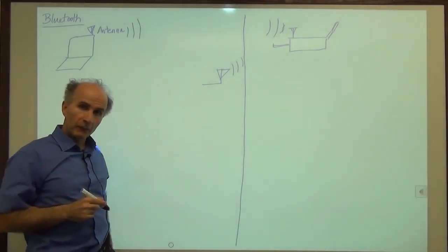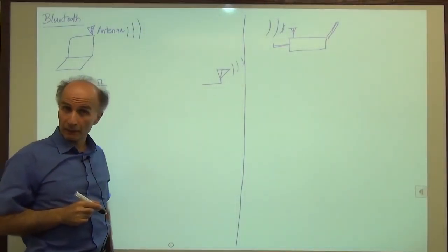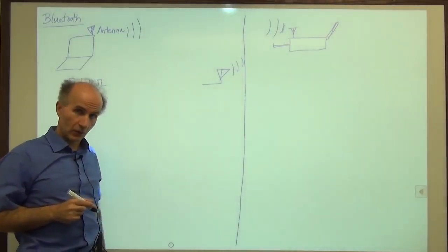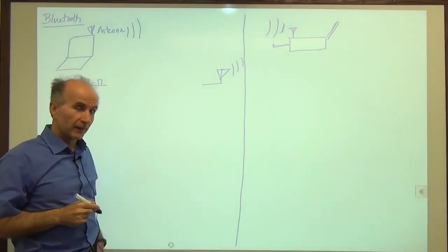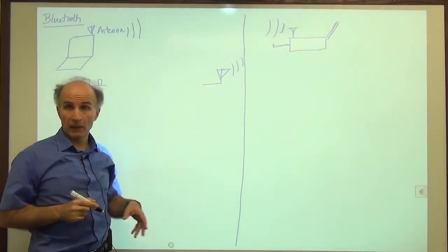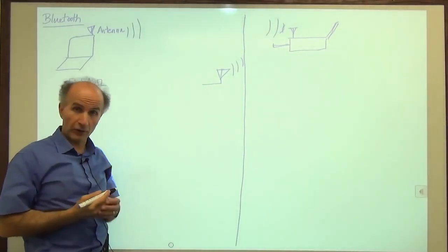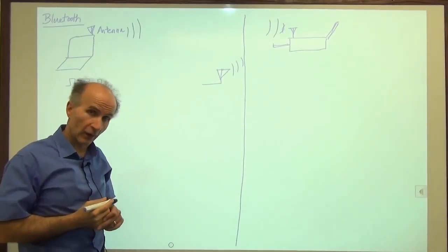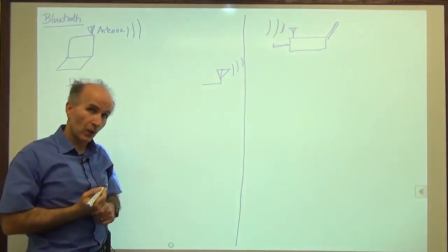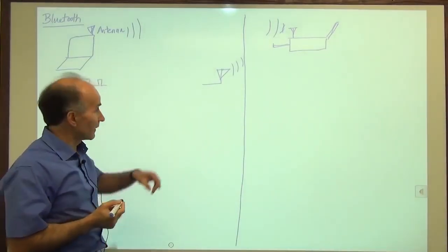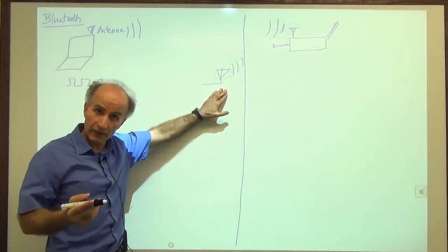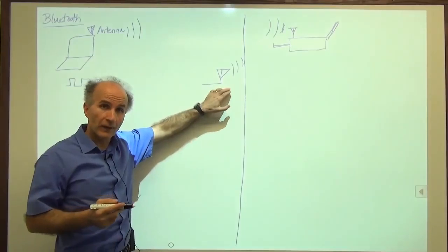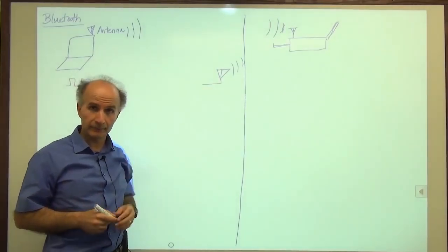Now, if you recall, in the cell phone description in lecture 1, we talked about the fact that the antenna becomes a good antenna or a good radiator of electromagnetic energy only if the signal that is arriving here has a wavelength comparable to the dimensions of this antenna.